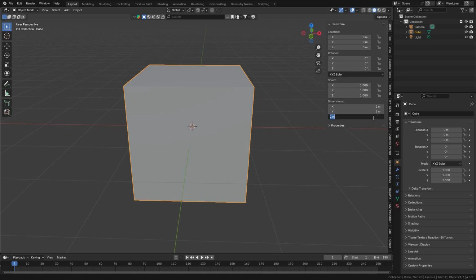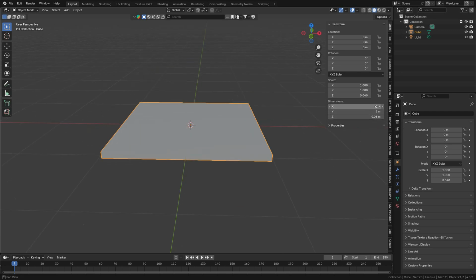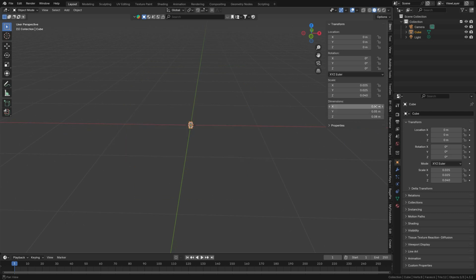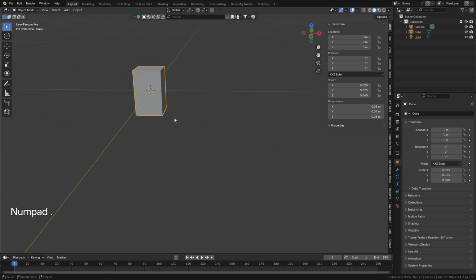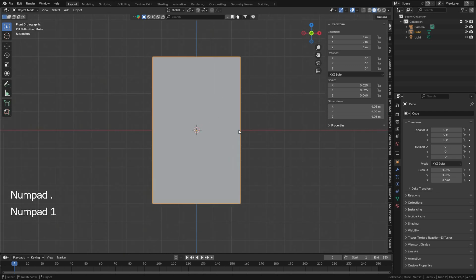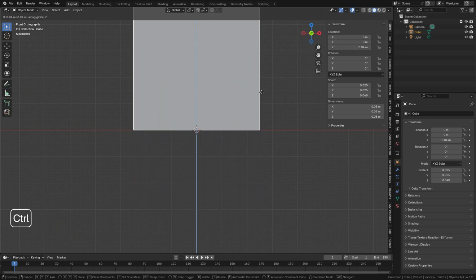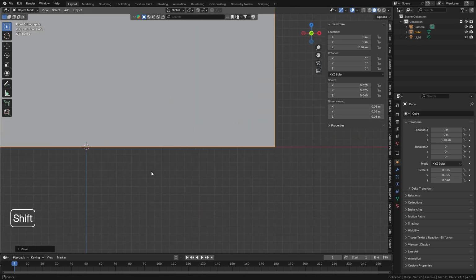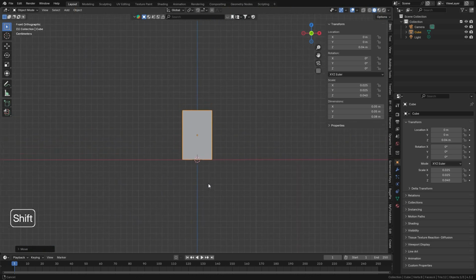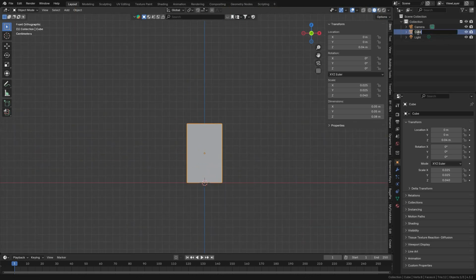So you have to reduce it. 8 centimeters will be the height, so 8 cm here, that's the height. And then in both of these, we type 5 centimeters and enter. So this is going to be the actual size of our toothpick holder, which is really quite small, but it's in real scale. Alright, so let's get to it. All I have to do is press G Z, bring it up here, make sure it's just on the line there. Yes, making sure that it's correct. It is. Then you can call this reference.